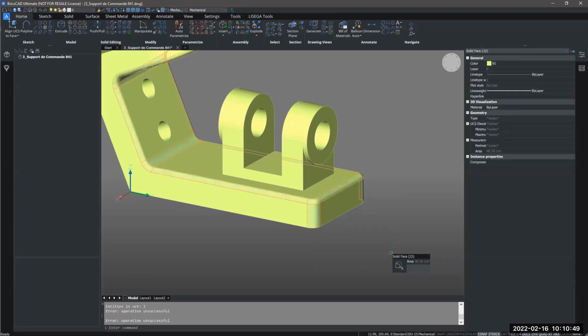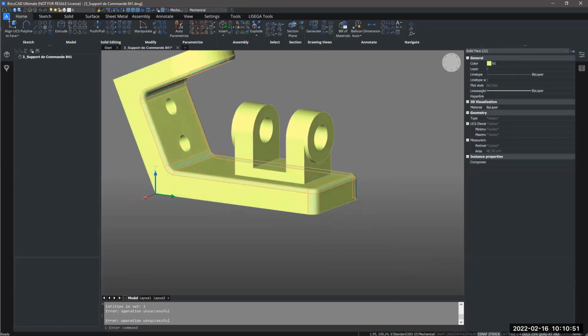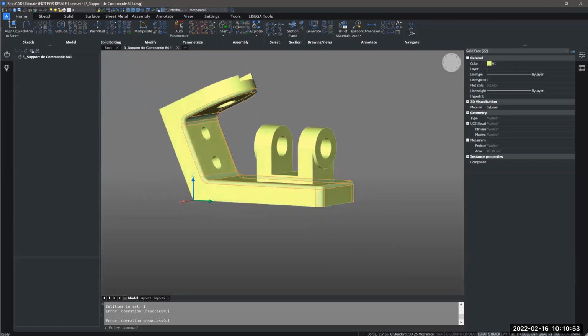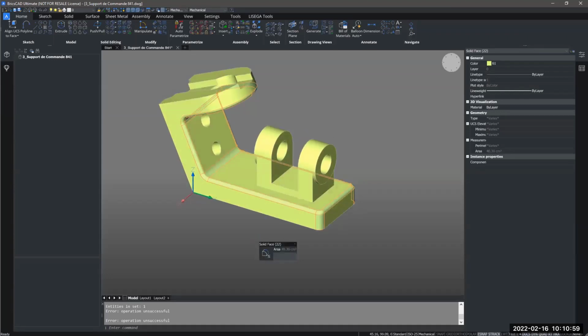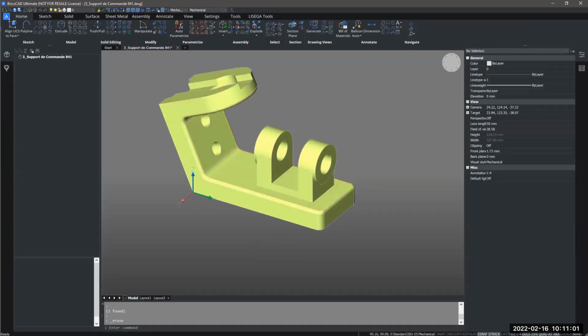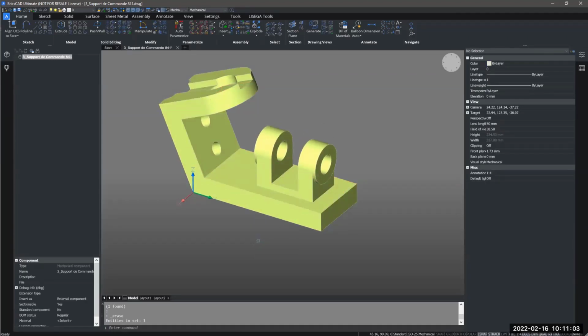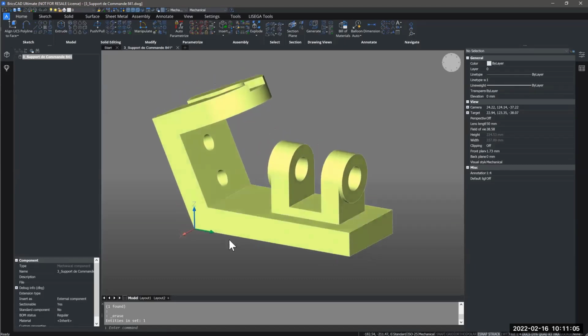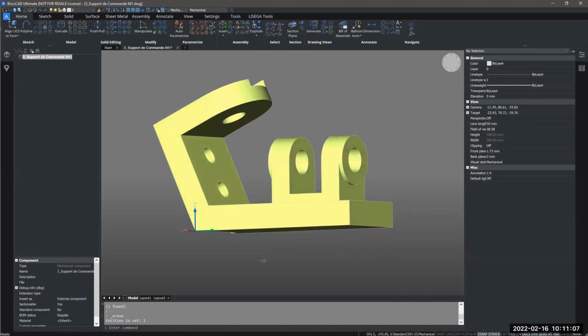By enabling this, it will select all the other radiuses or radii that are either equal to this radius or smaller. So now, very conveniently, all of these have been selected for me. I can simply select the delete key on my keyboard. And there we have already simplified all the radii.